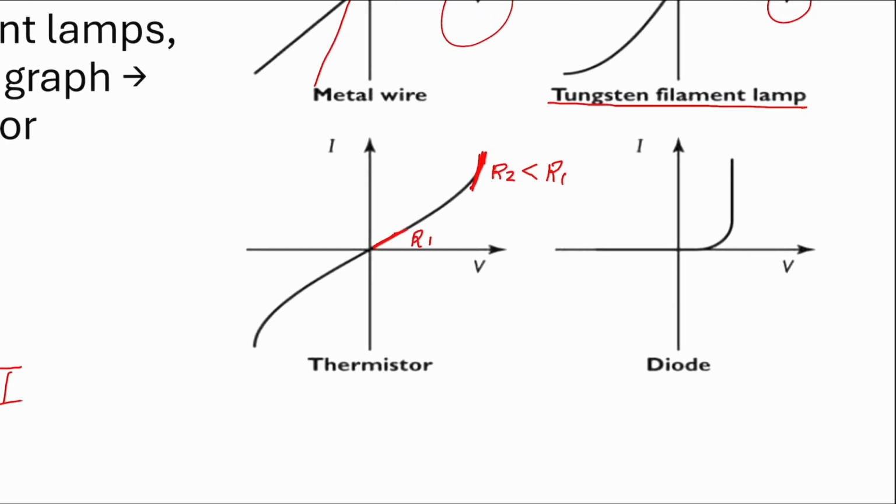Here, this is another type of material, and this is not a single material. This is called a PN junction. It's a very complicated semiconductor modified by impurities. Now, if we push a positive current from one side, here, if we say this is positive, in the beginning the resistance is very high, so the slope is very low. And then suddenly the resistance becomes very low.